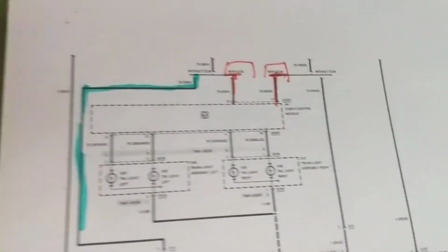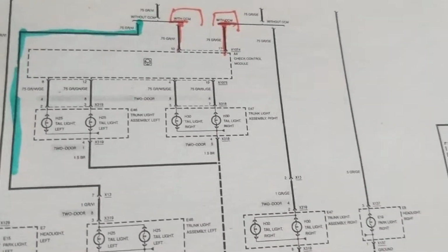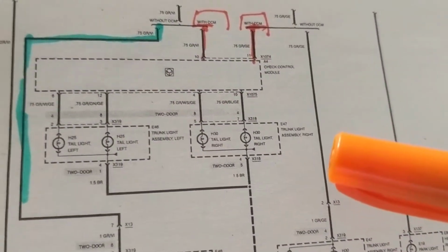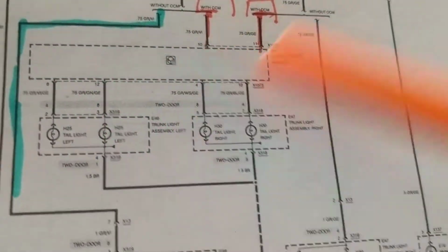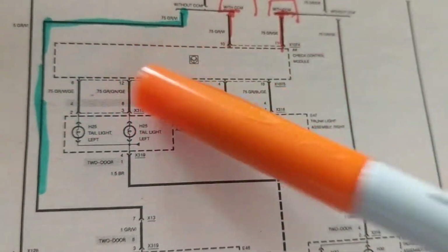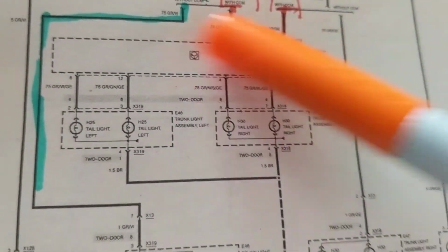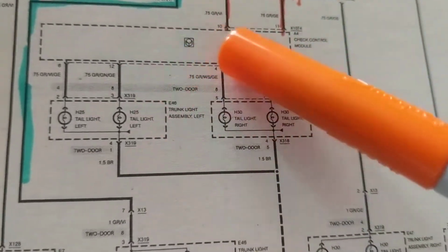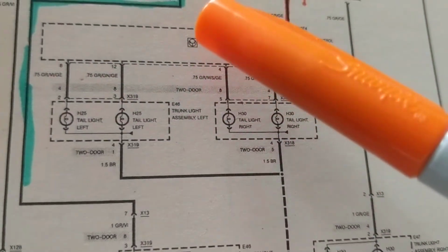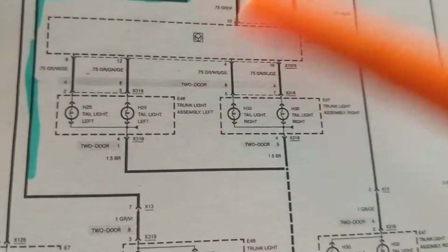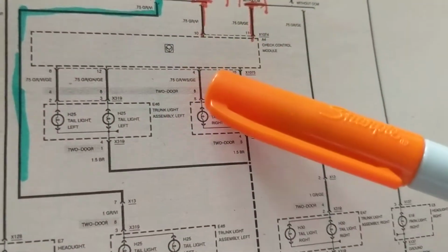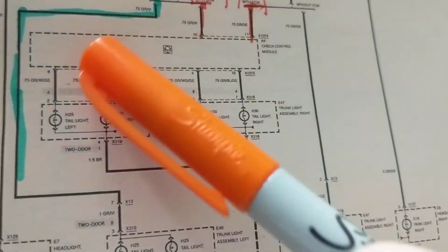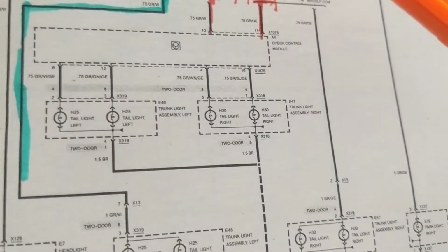Okay? So here I use knowledge of how to read automotive schematics without knowing, again, what CCM stands for, and without even knowing what's in here. The fact that it shows a transistor here tells me there are switches here. Do I care what really is in here? No, because when you work with something, you're going to change the whole module. So it doesn't matter to me what the transistors are in here, but just to understand how to analyze it, I would figure these are not amplifiers, but these are switches. Of course, I'm going to change the whole module, not the individual components in it.